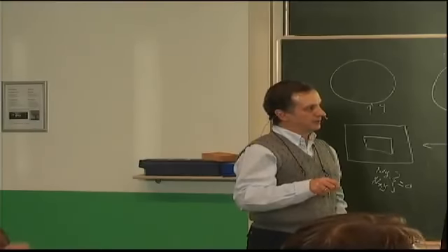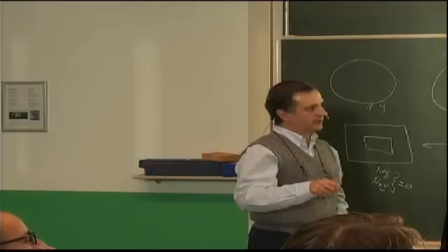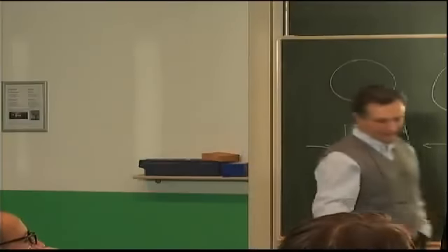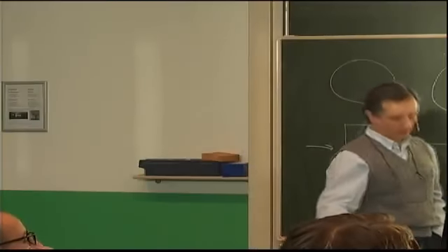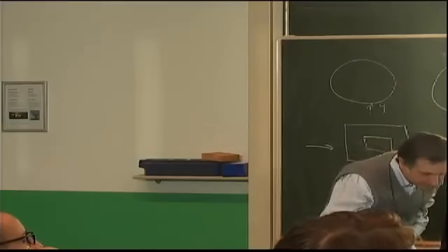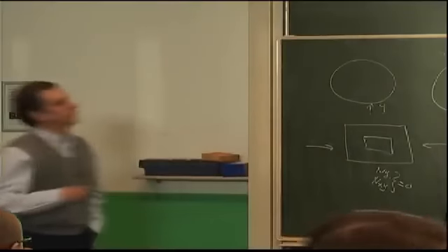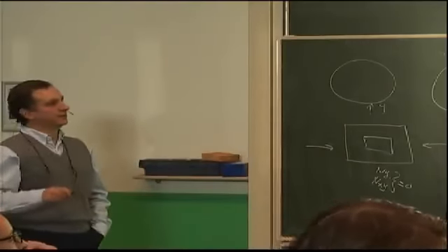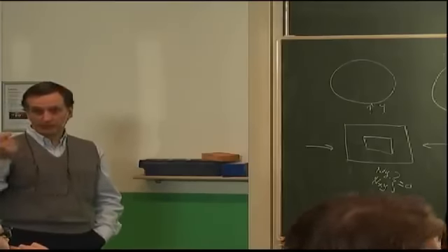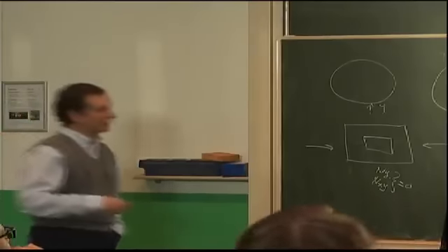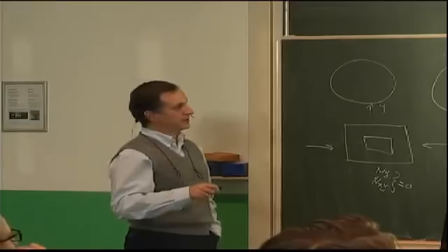And for our problem, we do have Nx applied, we do have Ny, but our Nxy is 0. So if I take this equation and remove these terms, I will end up with this governing equation for W. My boundary conditions, remember, now simply supported, and that means my W is 0 all around the edges.